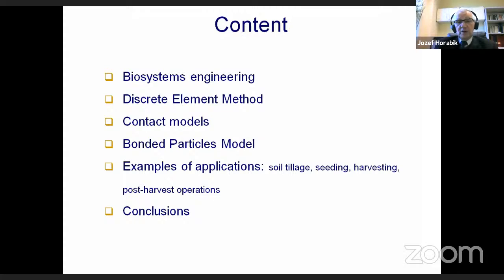So viscoelastic contact model is much better, which can be used for the wet grain, and with one equation, with the dissipation proportional to the velocity of the movement, the loading unloading loop represents the dissipation of energy. In case of the real materials, for example, wheat grain, we can observe from the experiment a very big loop, which represents the dissipation of energy independently on the moisture content of grain.